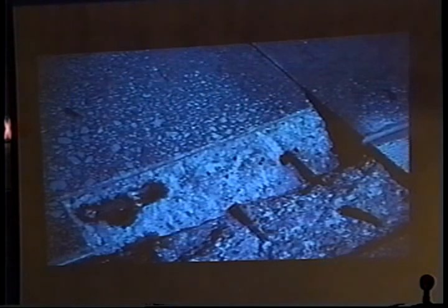Identify those areas for the patch. Come in with a lightweight hammer and cut that out after you've saw cut the perimeters to give you a nice, clean, smooth face to bond to. Jackhammer that out. This is the joint location right in this area. They've just gone back far enough and gotten down to firm concrete.